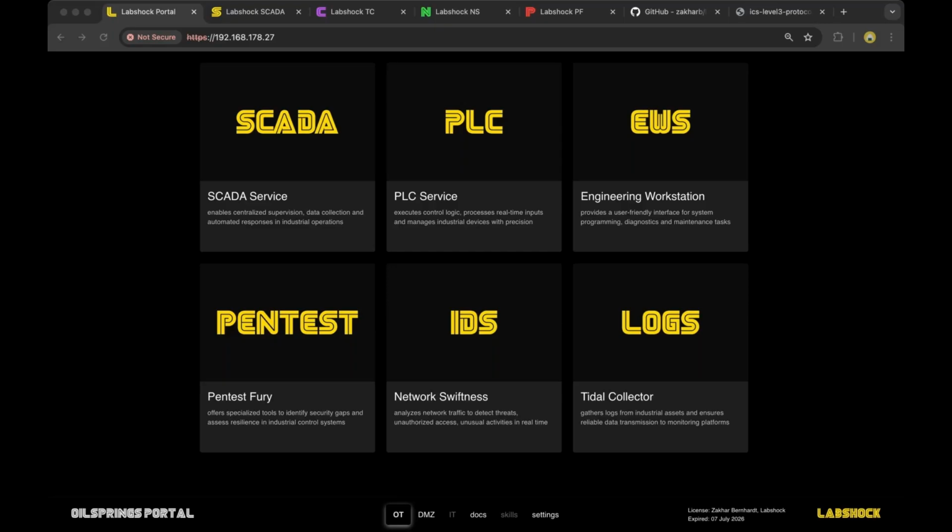What are the best practices for segmenting networks to protect Modbus? Make layered segments, VLANs or whatever, but at least segment your level 2 and level 3, or however you have these segmentations. I think you understand how to do the next segments. I mean, how an operator connects from the CCR to the other level. This is instrumentation engineering, the basics of OT. Don't understand.